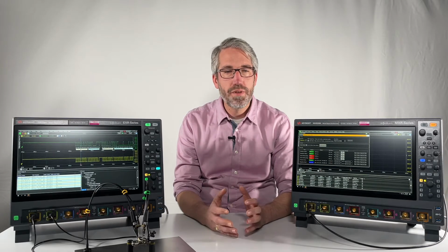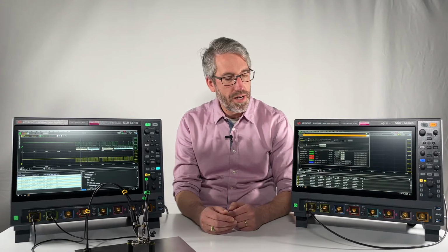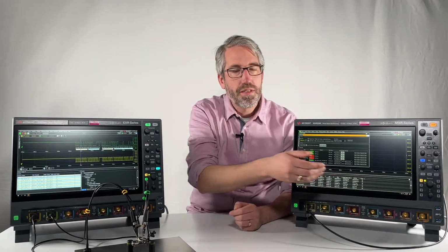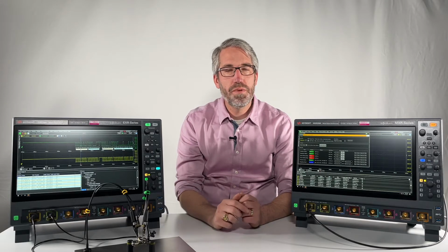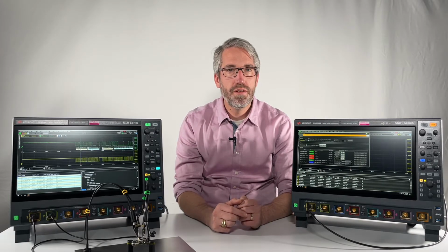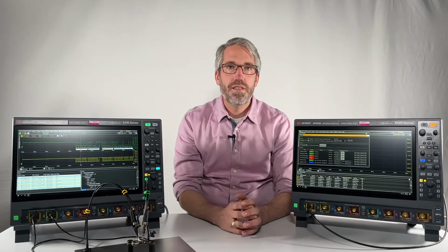Now, when it comes to confidence, there are two aspects on the oscilloscope which are important. The first one is the stability of the time base, because the time base stability directly translates to the horizontal axis. Basically, the spacing between the individual samples that you take is more accurate. When it comes to the vertical axis, this feature is equally important.